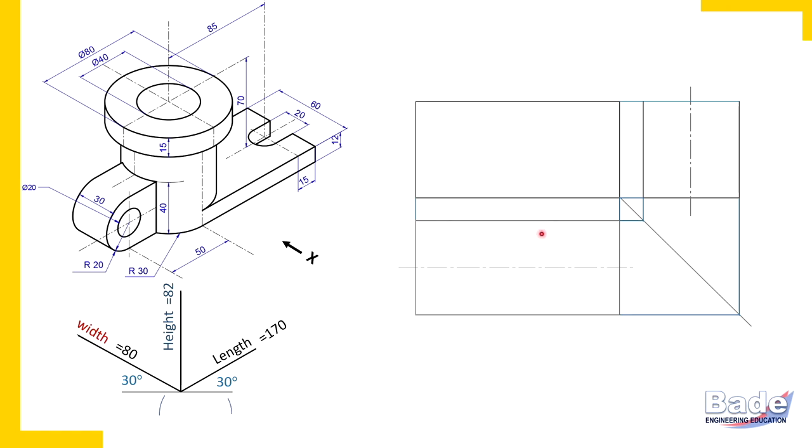And because these two sides are similar, we should draw the axis of symmetry in this manner, and the same axis of symmetry in the side view to be projected using that 45 degrees line, or independently you can also draw that axis of symmetry. So let's proceed.